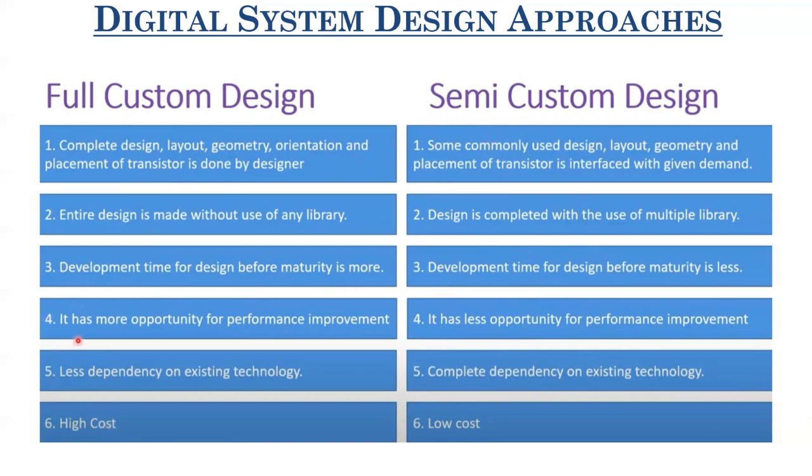Now, full custom design has more opportunity for performance improvement, definitely, because you have the freedom to design and place each and every transistor wherever you want. In semi-custom design, since it's done in an automated way, you don't have full control over where to place a certain standard cell. So it has less opportunity for performance improvement, and its performance even after the full design time is also low compared to full custom design. In full custom design, you do not have much dependency on the existing technology because you are doing everything on your own, right? However, in semi-custom design, since you are designing all the libraries based on the existing technology, you have a very high dependency on the existing technology.